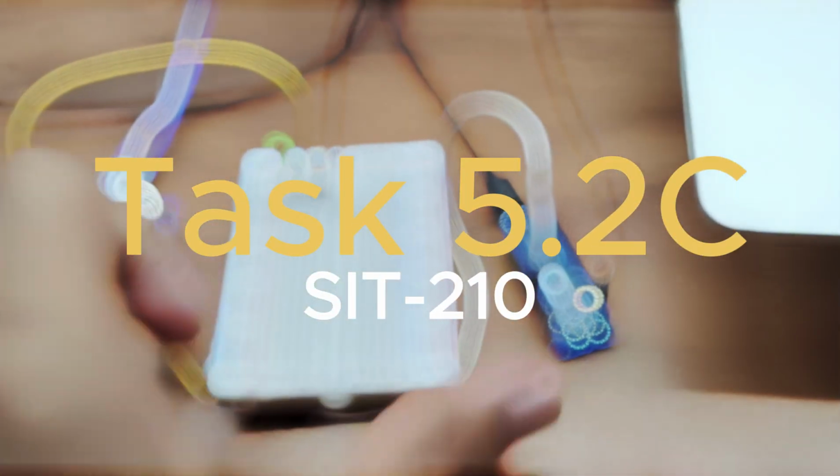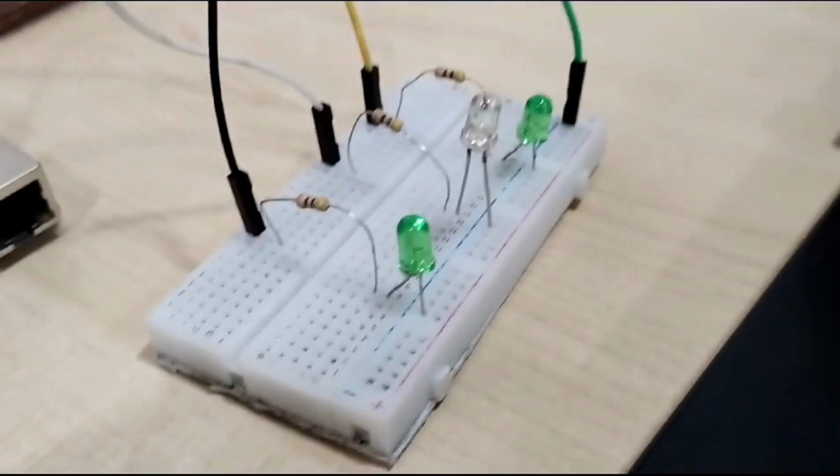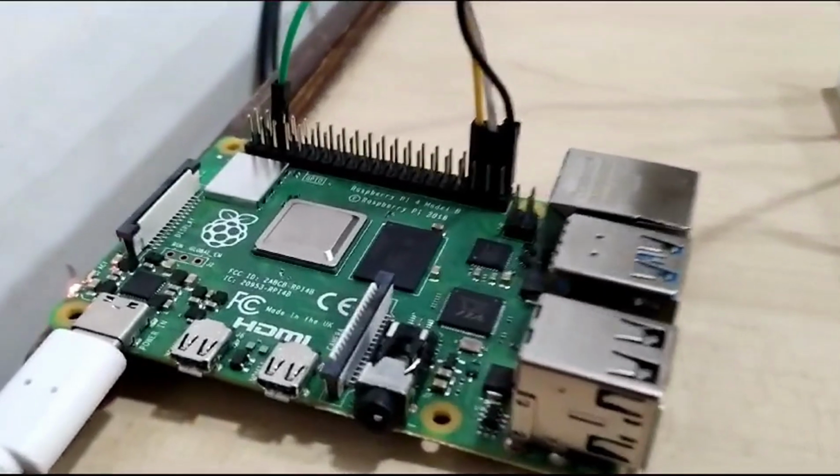Let's see the circuit. As you can see, I connected the three LEDs using jumper wires and resistors to the pin numbers 16, 20, 21 of Raspberry Pi respectively.